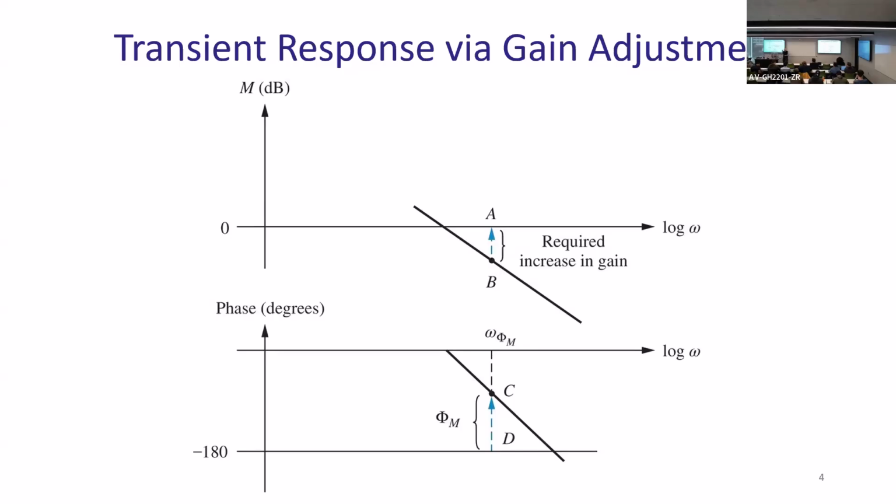Okay, so just find on Bode plot the point on the phase where it already fits your characteristics that you want in the first place. Okay, like don't compute phase margin, don't do anything with the original open loop function. Just find point on the plot where it already matches what you want in terms of phase, and then modulate the gain in such a way that it will cross exactly at that point.